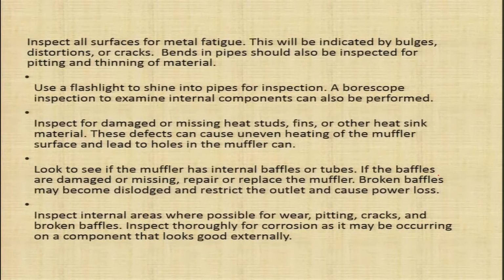Look to see if the muffler has internal baffles or tubes. If the baffles are damaged or missing, repair or replace the muffler. So, the muffler internal portion is also to be inspected. The baffles should not be broken. Broken baffles may become dislodged and restrict the outlet and cause power loss.